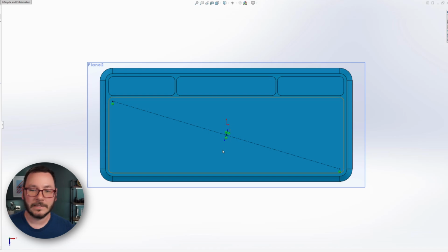What makes the rib itself unique is that it has 3 of those. So it's looking for where the bottom is, and it's also looking for both of its edges. So it's constantly monitoring how far it can go in all 3 directions. So that's a huge benefit to us in a case like this, where we're trying to have it fill a space. But also is something that we'll need to consider as we make some changes to this, and we'll get to that in just a moment.